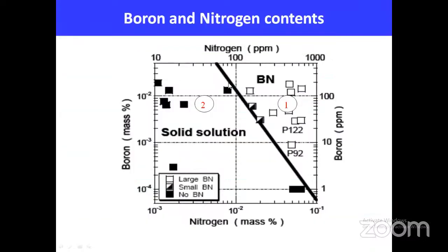If we add boron in the steel, will it benefit us with better creep strength? If we add boron, it should be present as a free element in the material. It should not form boron nitride. So we need to adjust the alloying and control the nitrogen, so that free boron is available in the material.